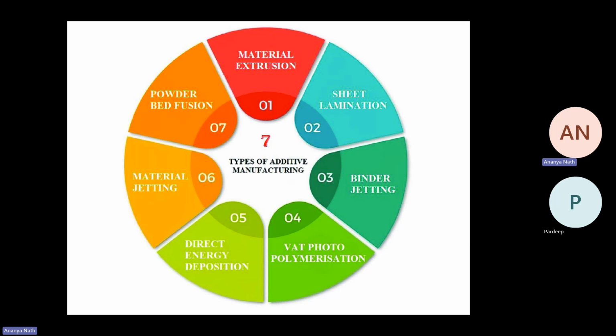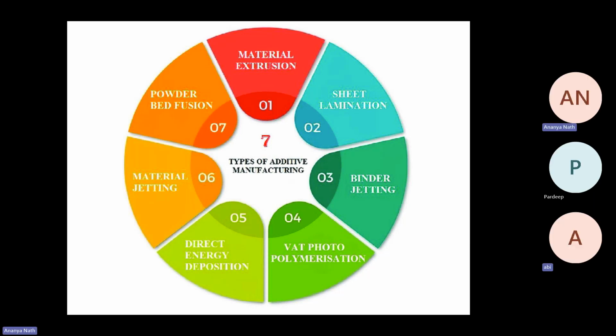The energy source can be a coil, like induction based or resistance based heating, or laser, high energy plasma, electron beam, arc, or even UV light. These energy sources directly interact with the metal powder and the material, whatever the raw material is, and cause the material to be melted and solidified.